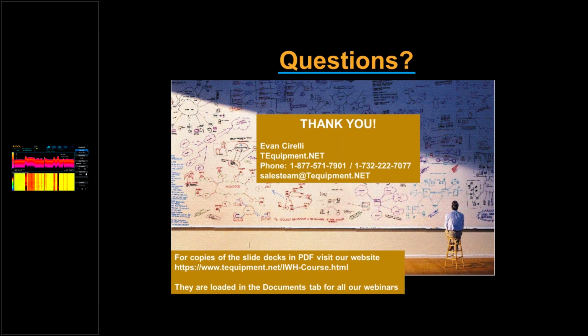We didn't talk too much today about the swept mode analysis, but this analyzer, I'm sending it over now, does both general purpose mode and swept mode. And what I really find useful, and I was doing some of it live for some customers last night, is the ability to do a full span sweep in a millisecond, like it's doing here, and then immediately pick out the area of interest, right?